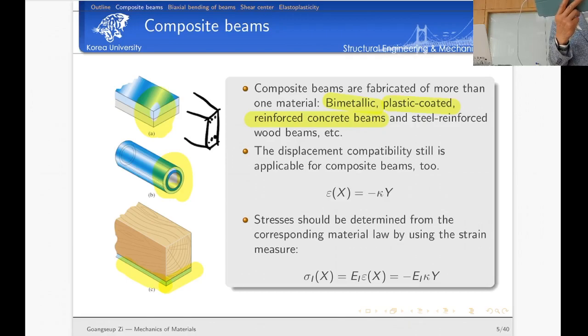Then if we have a strain field, the next step, we calculate the stress. And then if you have stress, we calculate the internal forces. And then we check force equilibrium with the external forces. The same procedure is applied even to this problem. Okay? No difference, okay? So now let's talk about the definition of deformation first.